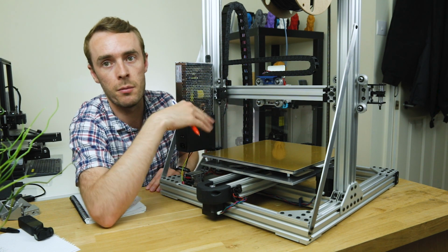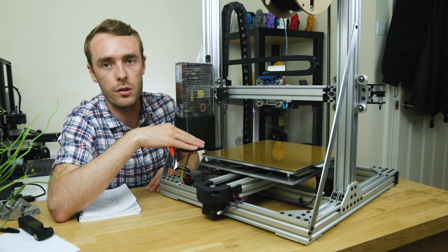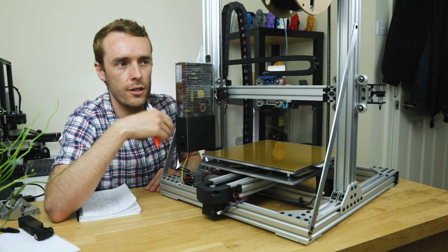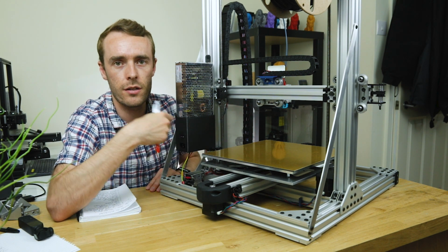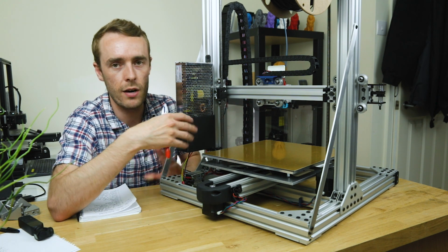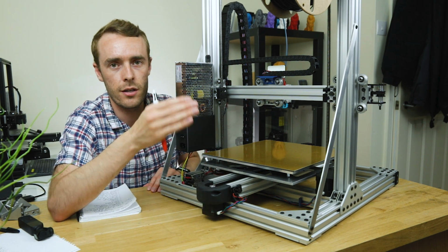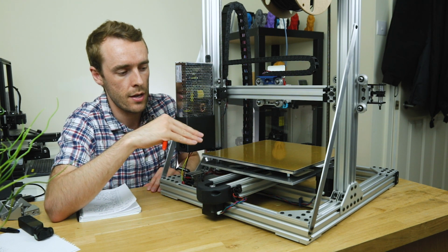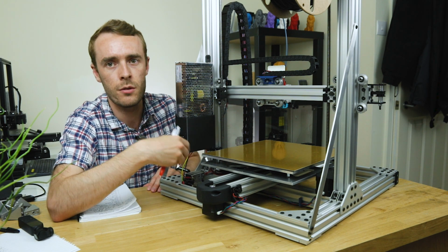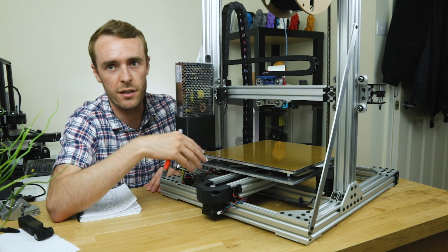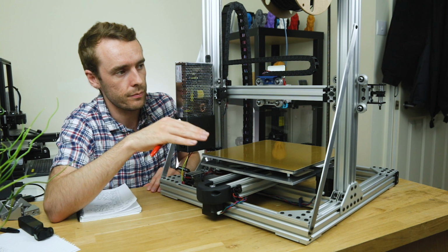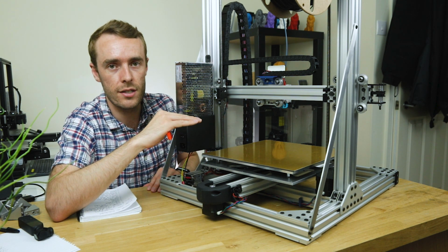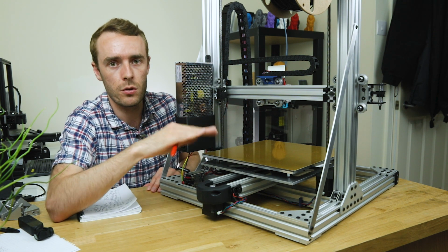So the first layer at the moment prints absolutely perfectly. When I took this up to 3D Meetup UK, I didn't even do any calibration once I got there. I literally had thrown it in the car, driven for 3.5 hours with it all rattling around in the back of the car, got it out the other end, slapped it down, print, perfect first layer. So in terms of being able to get that first layer, not a problem. It's a very rigid frame, very rigid bed, does a good job. But I think at the moment the amount of adjustment that mesh bed leveling is having to do is more than I want it to do.